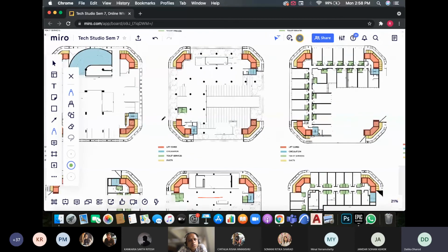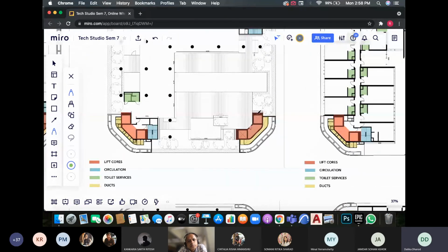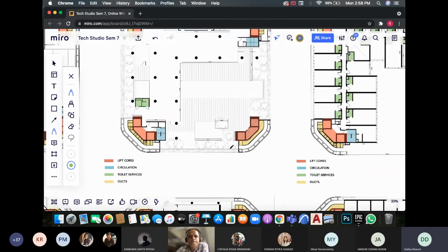Okay. So the actual stiffness of the building is offered by these corner cores. Yes. So look at the reinforcement, the RCC shape of these corners itself, and you will understand how that is working for the seismic. Okay, yeah, all right. We'll do a study for that reinforcement. Okay, thank you.